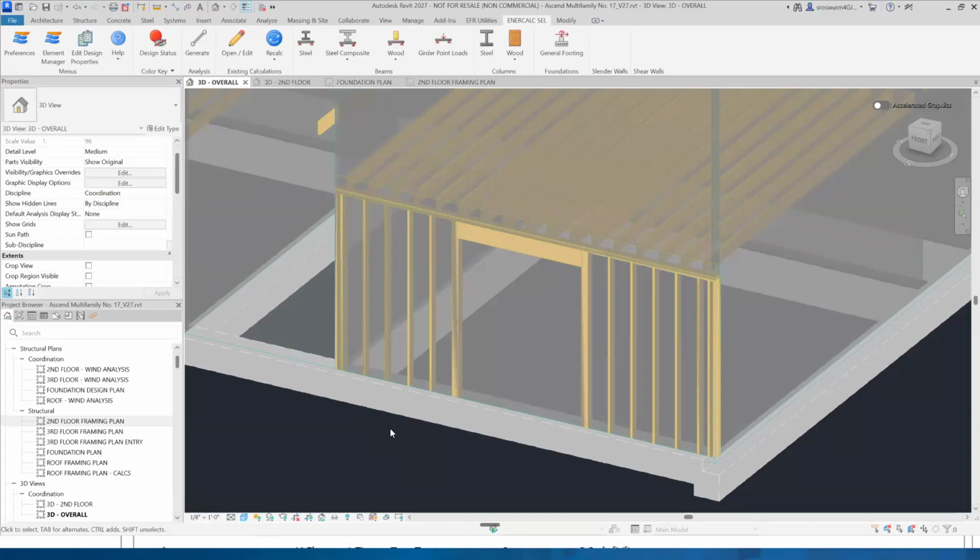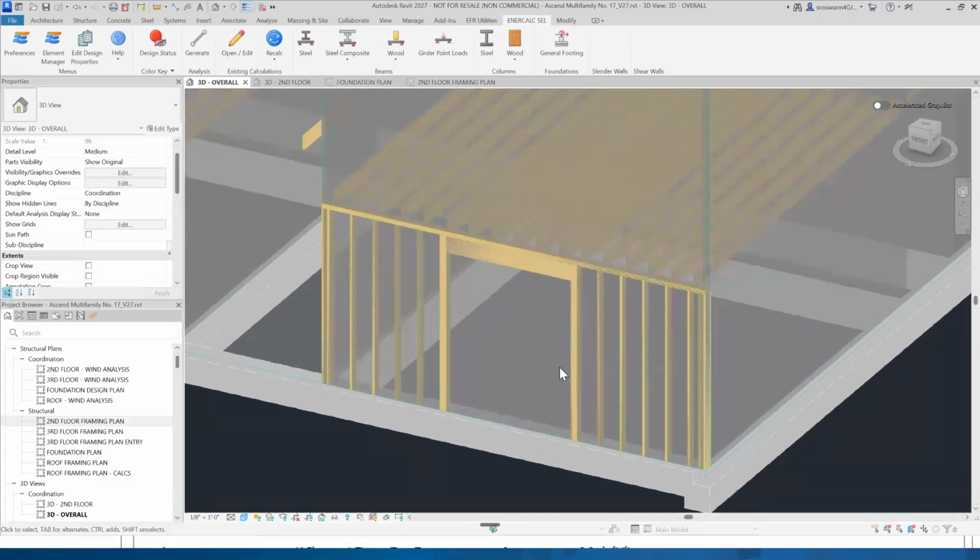And EnerCalc actually doesn't have a stud wall design module where you're designing the wall as a system, right? We do have NDS wood shear wall, but that's kind of a different animal. When it comes to a gravity bearing wall, EnerCalc doesn't have a module that does that per se. What you do have is the wood column module, which is a discretized individual piece axial compression element. That's the only reason why I had that set up the way it was, because that's in harmony with what EnerCalc already does today.